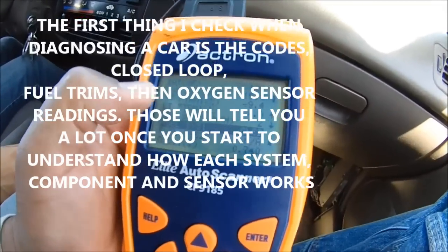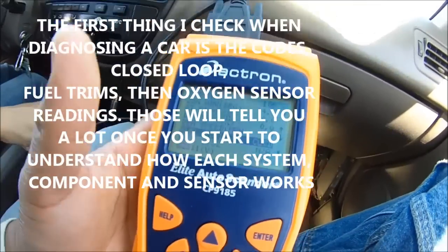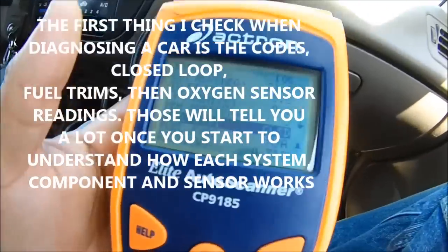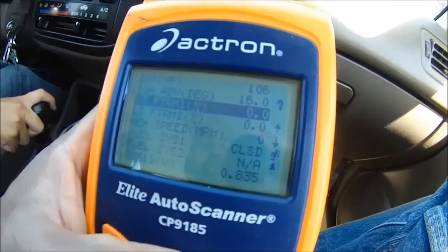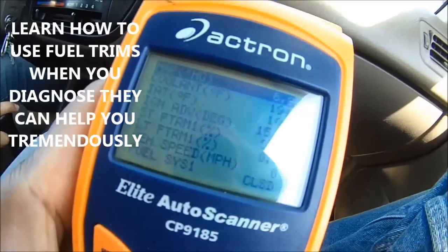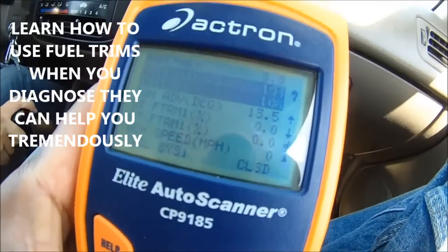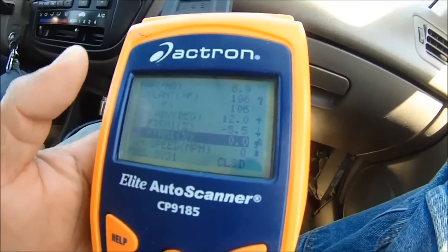But that was just real fast, if you noticed. And that's the system right there of open and closed loop. It's that simple. Remember these fuel trims here. You've got to master those. You've got to learn what makes fuel trims increase and decrease, okay? Hence the name trim. You've got to find out what makes them trim, whether it's lean or rich.